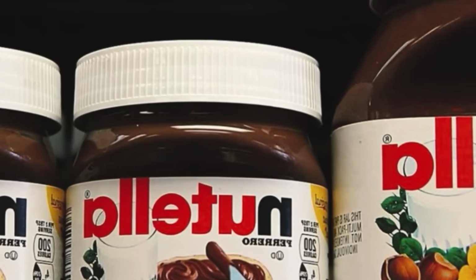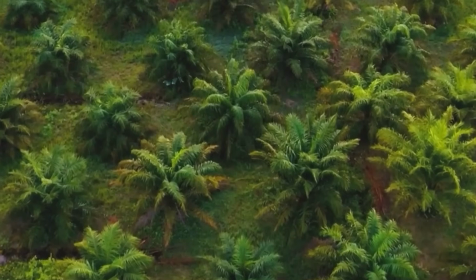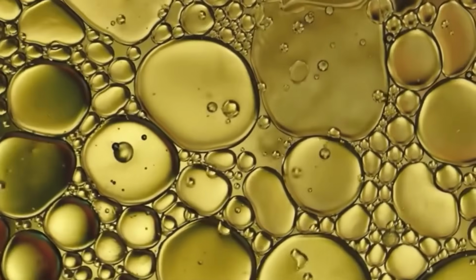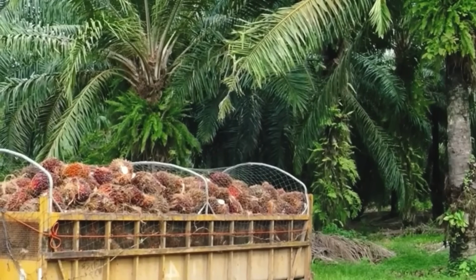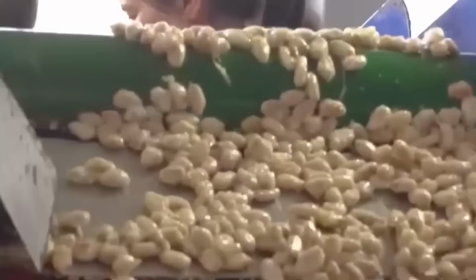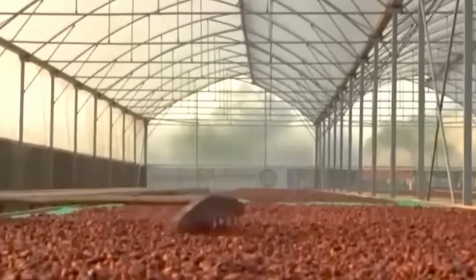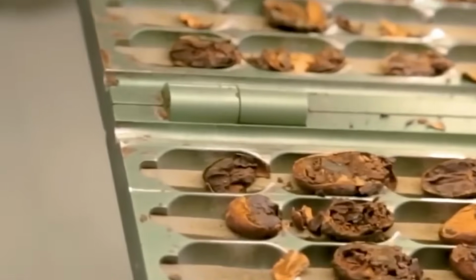Packaging begins with flow wrapping. Individual Nutella B-Ready units are spaced on timing belts and fed into the wrapping machine using servo motor controlled pushers. Wrapping film is fed from a roll and formed around each unit via a forming collar. Horizontal and vertical seals are applied using heated sealing jaws that operate at 130 degrees, 145 degrees.